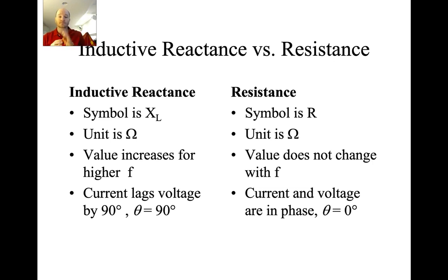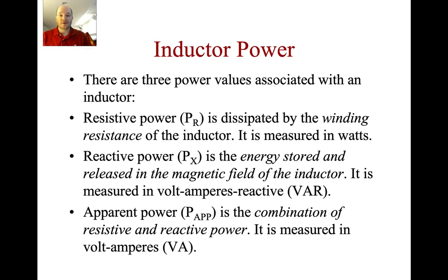All right? For inductive reactance, current lags the voltage by 90 degrees, or you could say that voltage leads by 90 degrees. Okay? In a resistor, and this will become very important next week, your current and your voltage are in phase at 0. Okay? All right. Very cool.